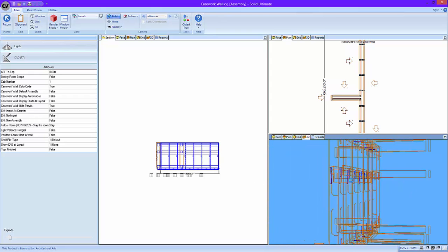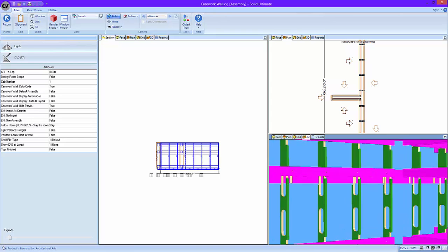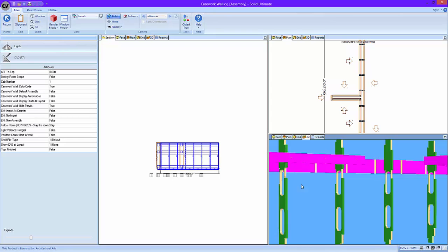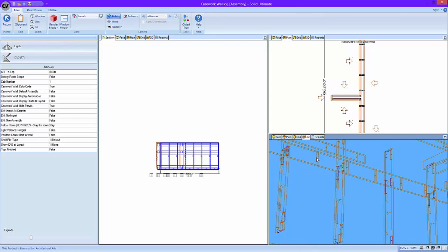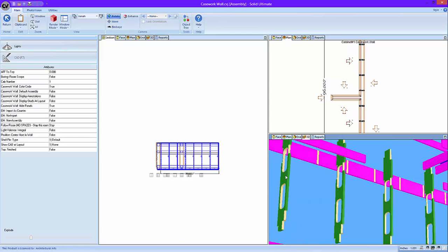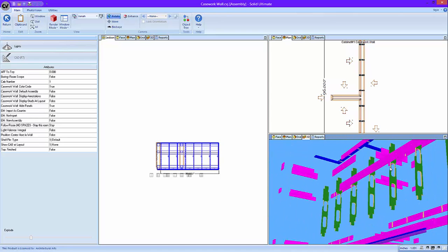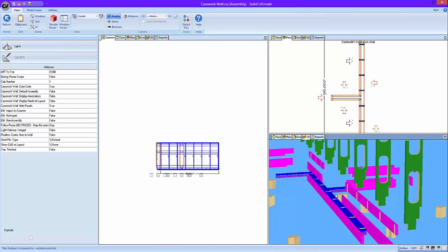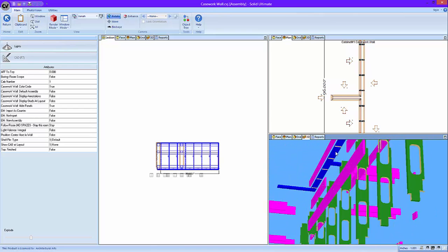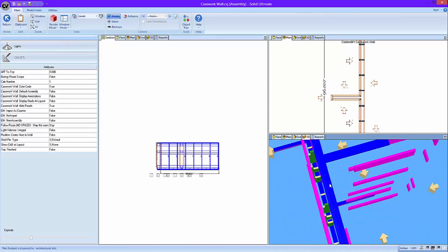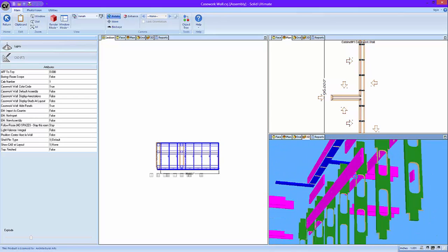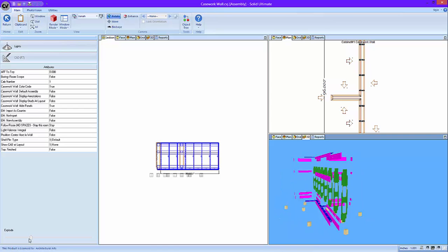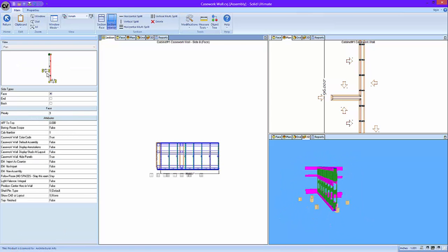The intermediate cleats, and then not the top and bottom, are being plowed out and have a screw hole drilled into them. So they'll fit into this notch. And the bottom and top plates are likewise being plowed out and have screw holes. Makes for very easy assembly. Let's put that back together quick. We'll finish studding this out.